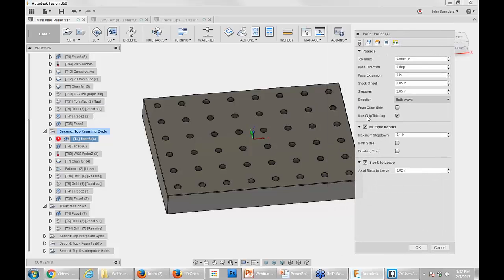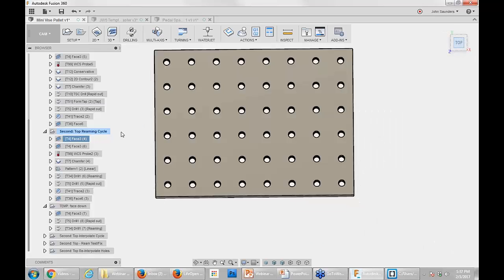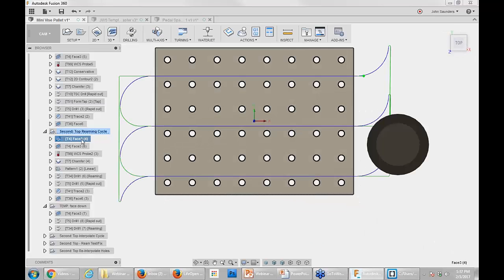Yeah, so under the facing, there's a thing called chip thinning, I believe that's it, which is going to roll your face mill into the part, which I believe helps with surface finish. It definitely, I'm told, helps with insert life, which when you start buying Sandvik inserts, all of a sudden you start caring about the insert life, because it ends up they're a little bit more expensive. But again, that's the dilemma. When you go buy a better machine, you want to feed it really good tooling to make great parts.